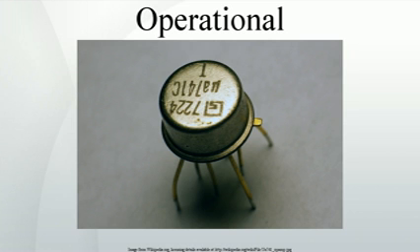Voltage amplifier. The Class A voltage gain stage, outlined in magenta, consists of the two NPN transistors Q15/Q19 connected in a Darlington configuration and uses the output side of current mirror Q12/Q13 as its collector dynamic load to achieve its high voltage gain.